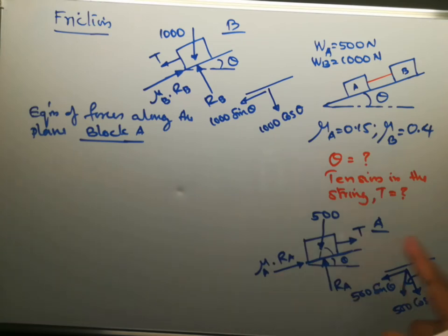So parallel to the plane, if we consider the forces and equate it to 0, because these two bodies are not moving now, they are just about to move. In the next moment they will be moving. That means they are in equilibrium now.